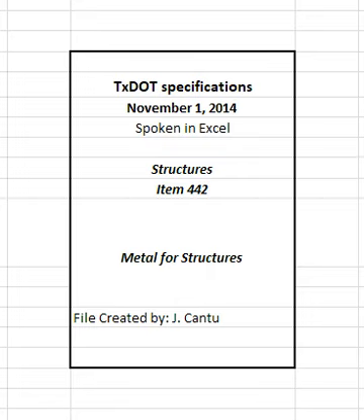2. Materials. Furnish mill test reports, MTRs, supplemental test documentation, and certifications required by this and other pertinent items. 2.1 Structural steel. The engineer may sample and test steel in accordance with ASTM A370.